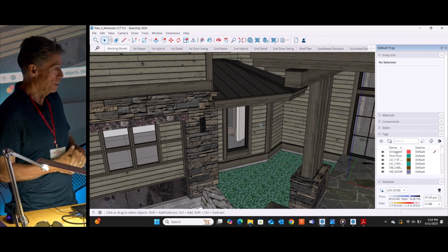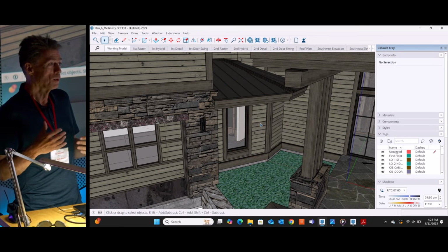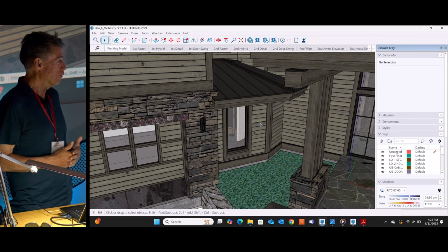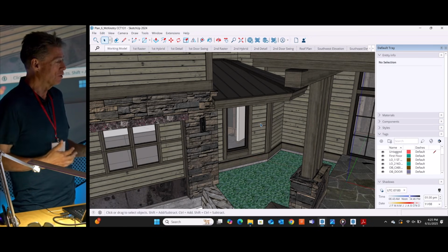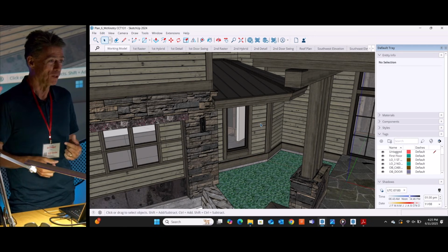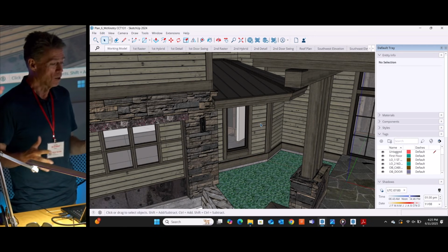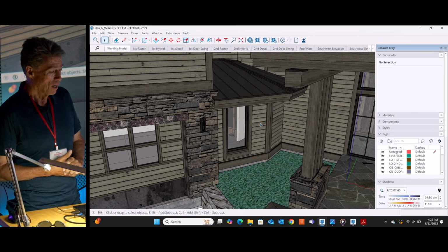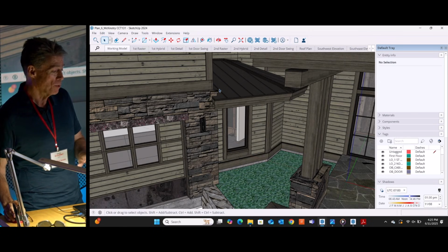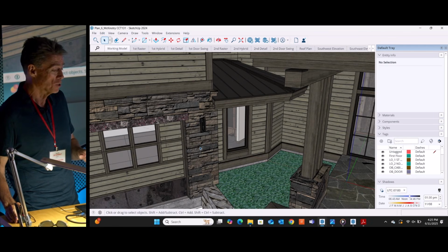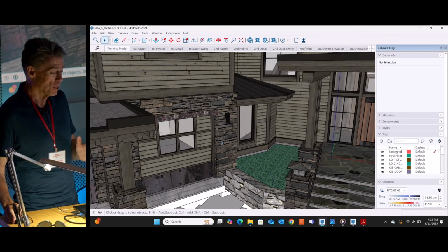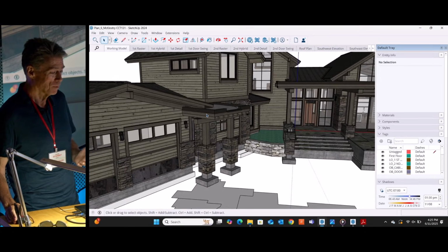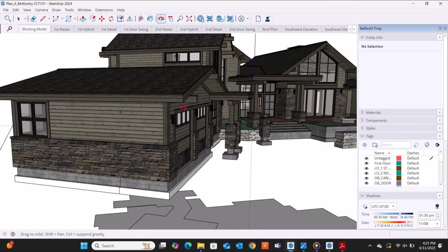And really, there's no need to model something that is just being added on to the frame, because once the frame is there, then they add on to it. Obviously, you have to be cognizant of things like clearances. If you want a closet to be 2 feet clear, make sure you're modeling it 2'1". And then the trim and the stone I do model because, again, for rendering purposes, that's what really gives it its feeling of reality as we render the project.